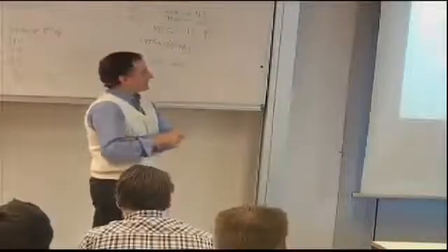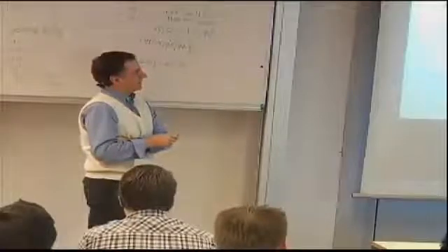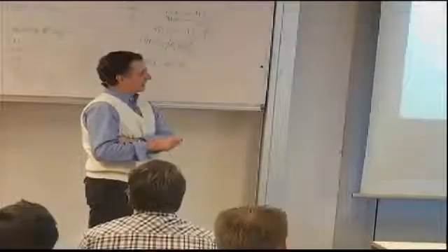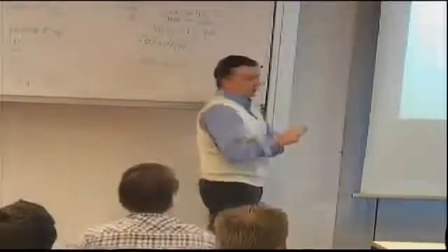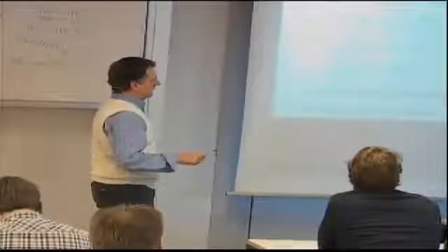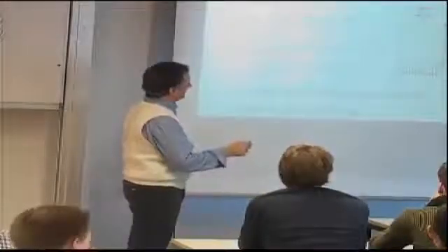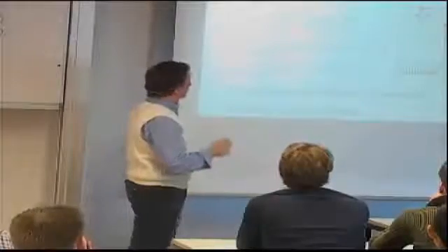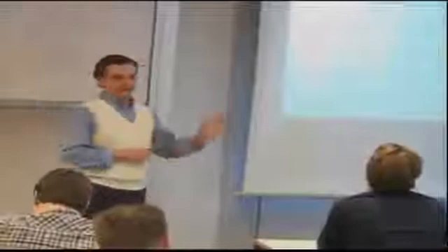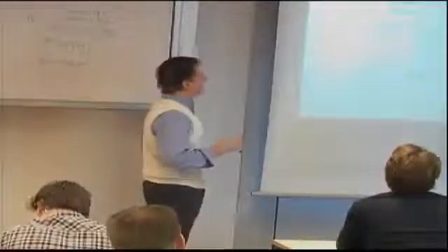Basically, K0 is by definition of Fourier series the average of the function sigma x at any x location. And that average is just the force divided by B times h, the thickness of the plate. So this, the total force divided by BH, is the average stress, and that's what this quantity, sigma x, should be at any x location. If I make a cut along x, I should still find the same value for the average, and you can check that by integrating. You'll find that the y dependence disappears and you are left with f over bh.